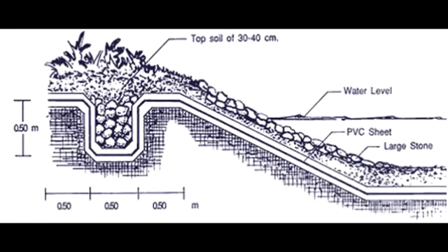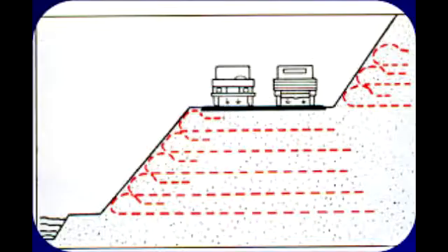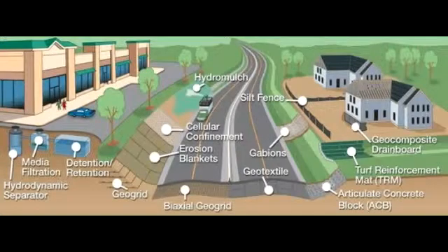These included the cases that we found related to these geotextiles, which is, in case 1, coir geotextile has been used to stabilize the soil in slopes, while for case 2, the soil needs to be emphasized on improving the strength mechanism and also the bearing capacity by adding the jute fiber and geogrid.